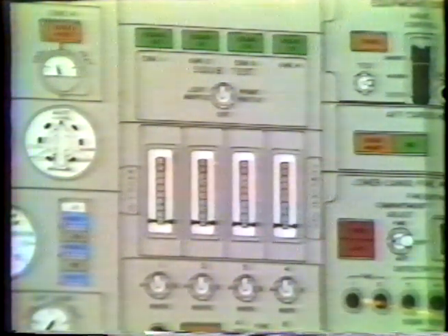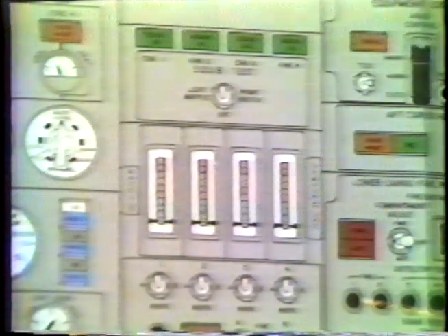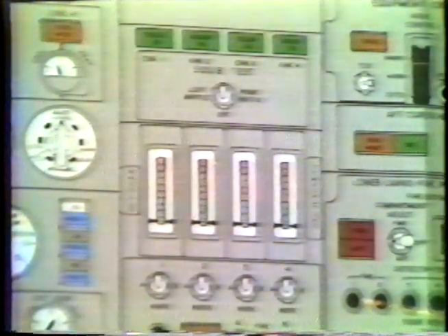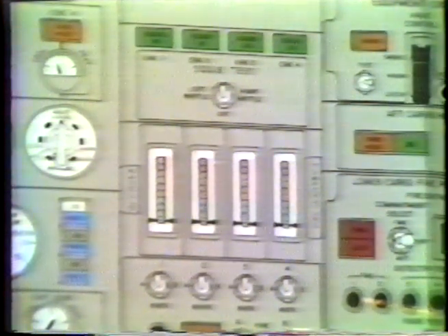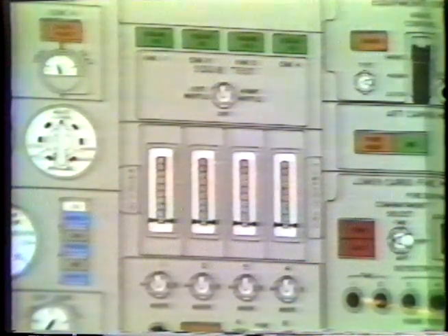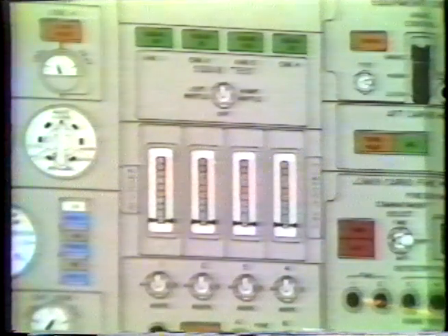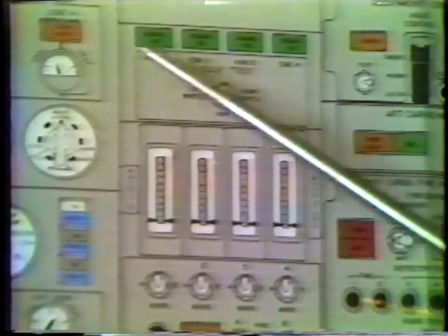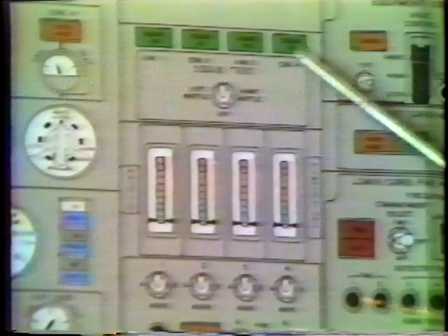To determine whether the bottle is good requires an outside walk around. On the right side of the pylon, there are two little red discs up there which indicate that a thermal discharge has not occurred. To technically check that the bottle is good, the bottle has to be removed and weighed. Okay, when we do the squib test, we go to the left, we get 4 lights. We go to the right, we get 4 lights.